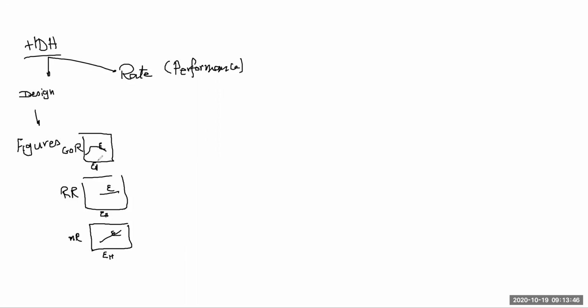And accordingly, you would be able to know if you are given the distillate flow rate, which is always the case. I mean, we say that we need to design an HDH system that can provide us with, the problem in the homework was saying, 1 cubic meter per day. I need a ton of fresh water every day. I would convert that into kilograms per second, and then that becomes our productivity.